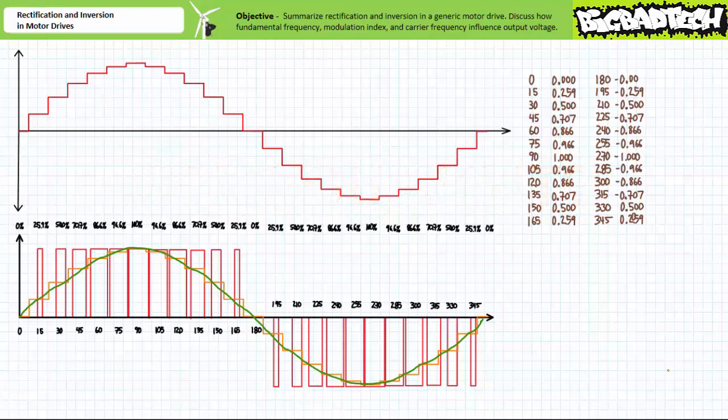The unfiltered output of the inverter is, as the name implies, modulated pulses of DC, where the duty cycle is varied to reflect the average values for an individual section. The filter then just smooths it out. A three-phase PWM inverter simply does this 3 times, such that three-phase AC waveforms have a respective phase shift of 120 degrees between each other.